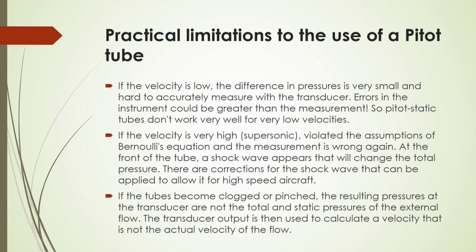Now, there will be some practical limitations to the use of a pitot tube. If the velocity is low, the difference in pressures is very small and hard to accurately measure with the transducer, and in this case errors in the instrument could be greater than the measurement, and pitot-static tubes do not work very well for very low velocities.